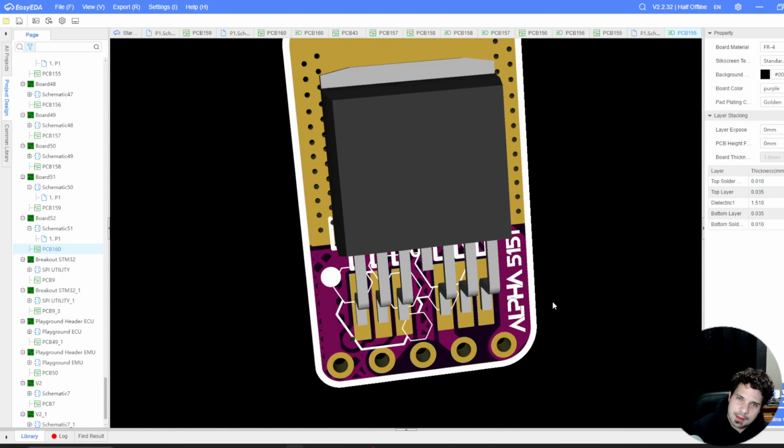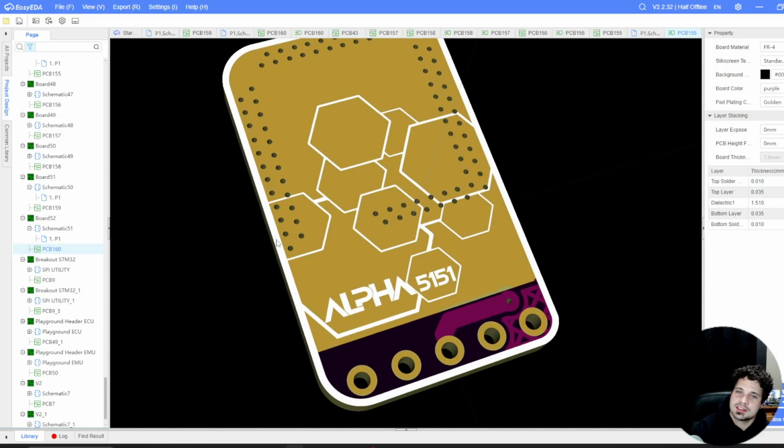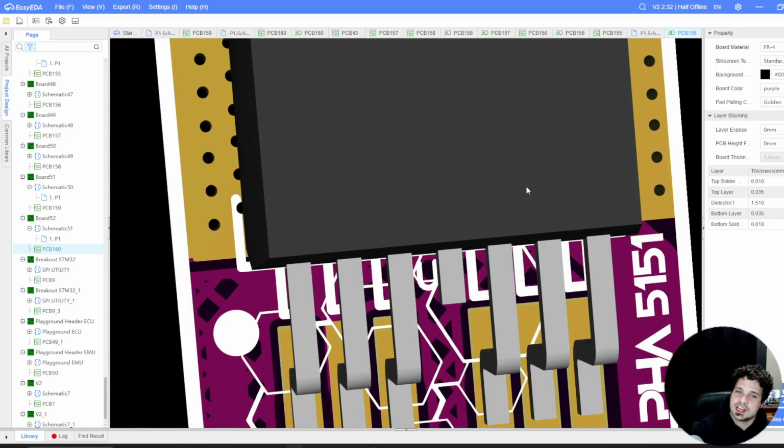And when something happens on the output side, meaning there's greater draw than it expects, like a short or a bad solenoid, it will actually set that pin high or to a 1, or it will introduce voltage to that pin. So this includes that diagnostic feedback pin letting the ECU know when there is a fault with it. So this actually mimics the entire original VTEC solenoid.